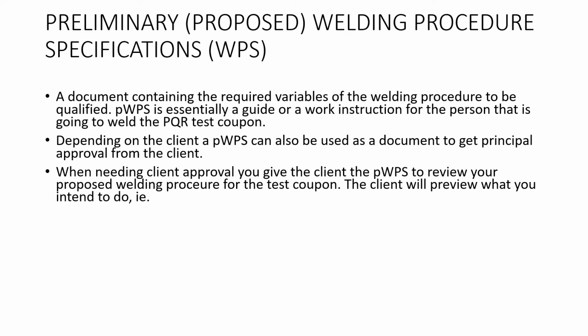When you do need client approval, you send the pWPS off to the client to review. Their welding gurus are going to look at it and tell you either yes or no. And a lot of times in oil and gas where you might not have a lot of material to experiment around with, maybe you got one shot at this, a pWPS is a really good idea. And that's why they do it, to make sure you don't blow through a long lead time piece of material that might take you 6 months to get. So that's one of the other driving forces behind a pWPS.